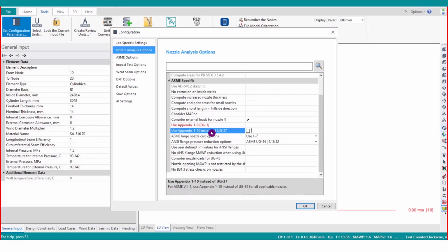But some of the vessels you might be doing were done, let's say, 10 years back, and now you are going to replace some of the parts, and if you want to keep the design code the same as the old one, these are the checkboxes that you can click upon so that the software can still perform the calculations with those guidelines. ASME, don't click upon any of the checkboxes. That is in a nutshell what we can say, unless you want specifically something to do.